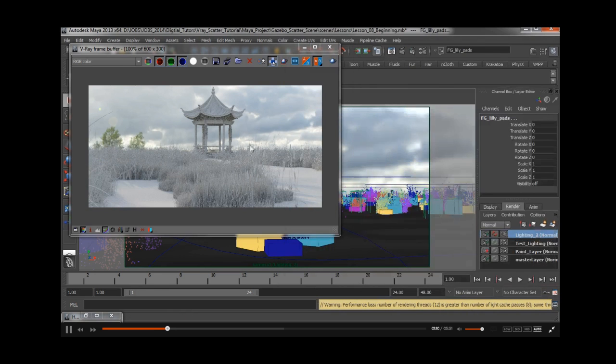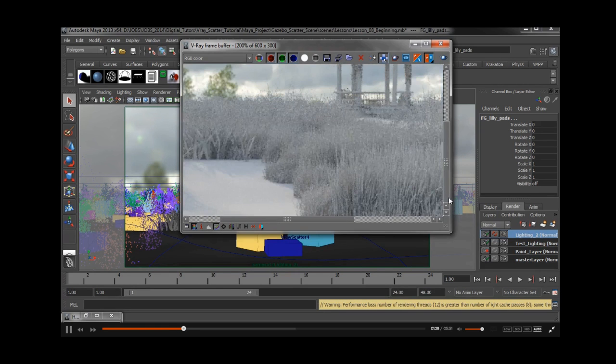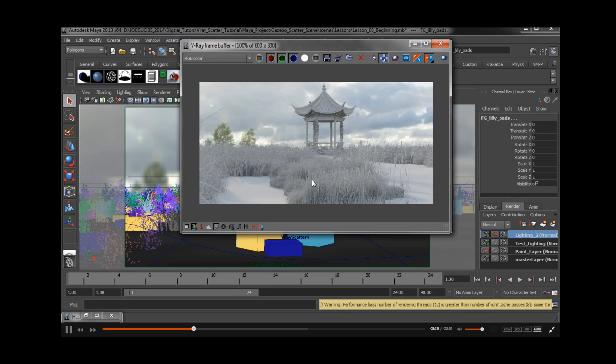And you can see here, pretty good, pretty happy with the lighting here. We can see the shadows that are happening from the V-Ray sun. The scatter is working out quite nicely, and the gazebo looks good. I think if anything, we're going to cut back on the scatters in this area and just try to see a bit more of the water, and also to be aware of it, this is going to need some breakup. So I might manually place some of those proxies just in areas here so we don't see this harsh kind of line. Just try and fudge it a bit by putting some proxies in front of it as well.